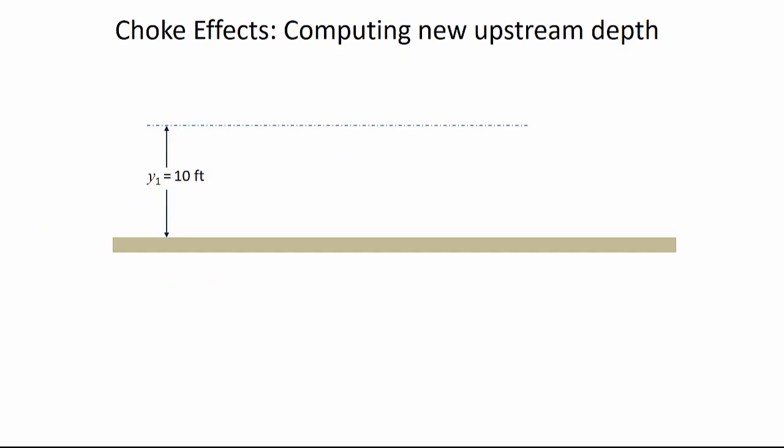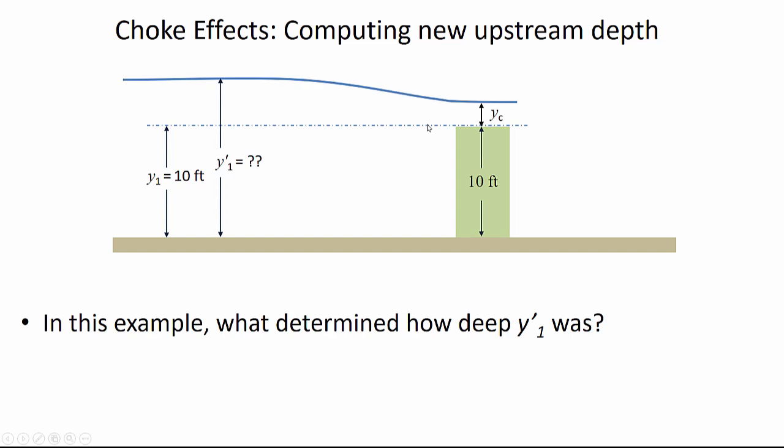So first, on the subject of an underflow gate, let's revisit the idea that we have flow going downstream under uniform, steady conditions, and so we have some flow depth. And in the past, we already saw the example of what happens if you put an obstruction in the channel. The principle was that if the flow upstream doesn't have sufficient energy to get over that obstruction, then the flow upstream is going to pool until there's enough energy for it to flow at critical conditions over the obstruction.